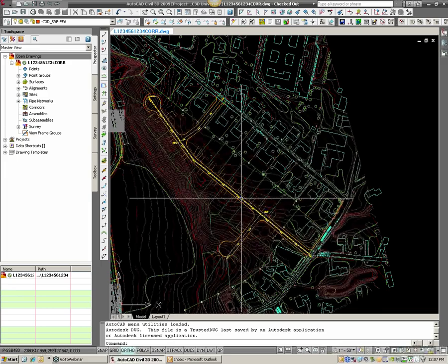And what I mean by that is, you come through, take a big swath through to clear things out and get maybe some bulk earthwork volumes, get those road profiles set. Then you come back in and maybe add the houses, figure out some first floor elevations, and that would be the steak knife step. And then the third step would be to use your scalpel and come in and put maybe the swales in between the houses and the grading behind it.